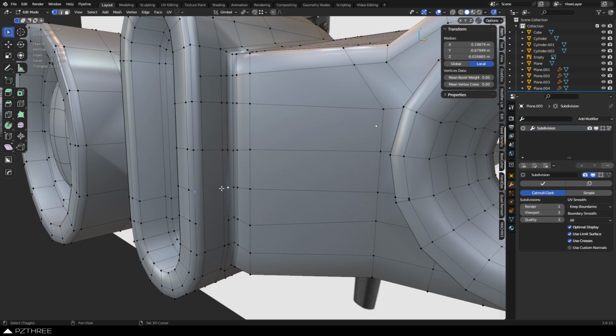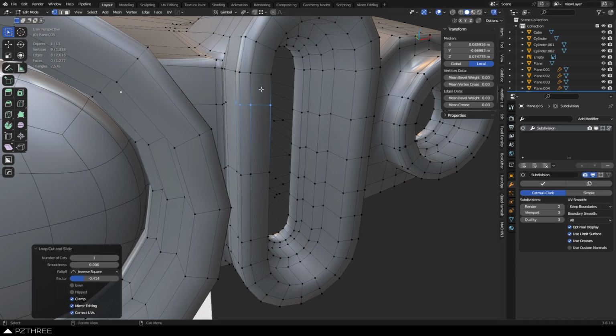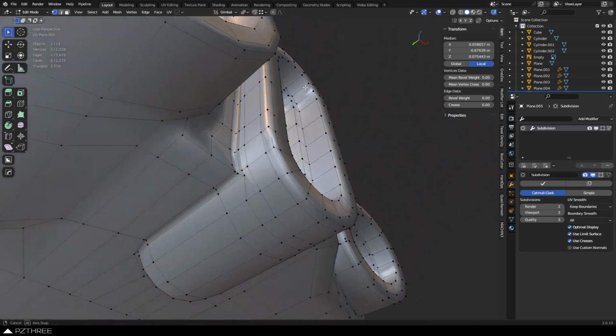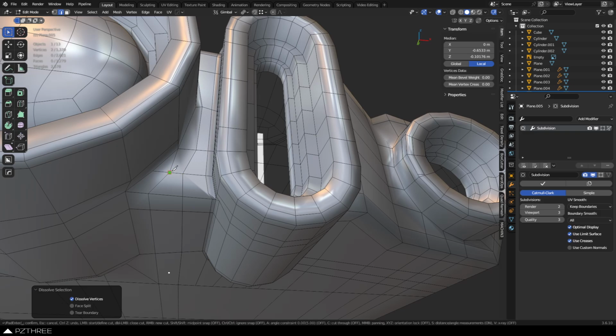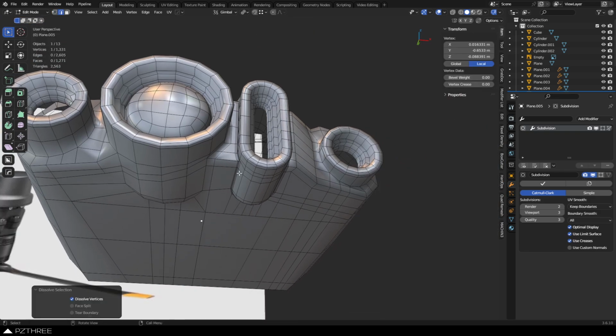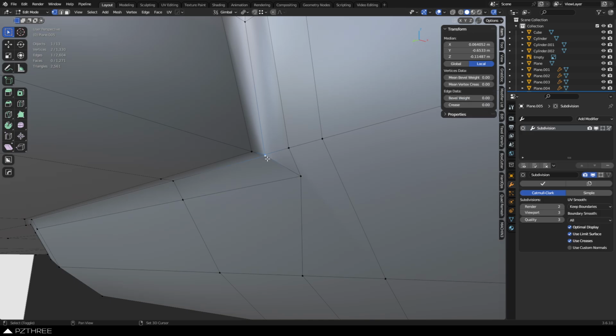Okay. You think we go through all this trouble and we'd have the perfect mesh and we're done? No, not really. What's going to happen is we still have a lot of little minor details to do that we did not hit in that blockout. And you can do these on a higher resolution mesh, but you can't do them on this low resolution mesh. So sometimes you're going to apply a subdivision and keep working this basically. That's a possibility. And if your quads are just not working out for you, they're not working out for you. So we can pull that one up there, maybe dissolve that to there. That can all go away then. You see how that works out? A lot of little things we can optimize still and tweak perhaps.